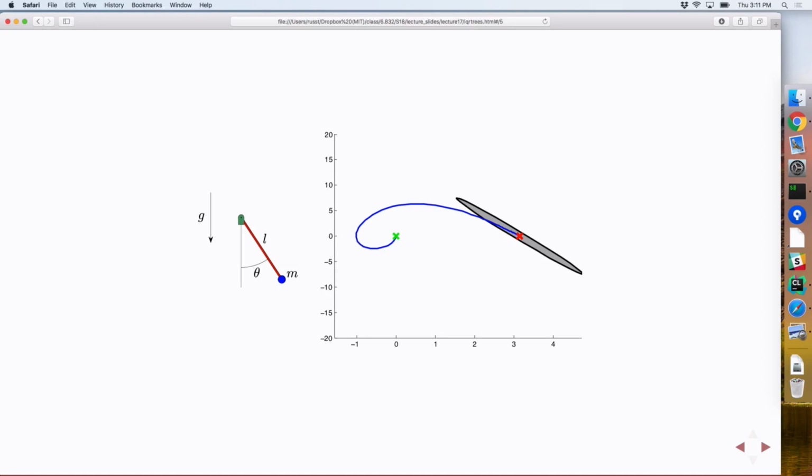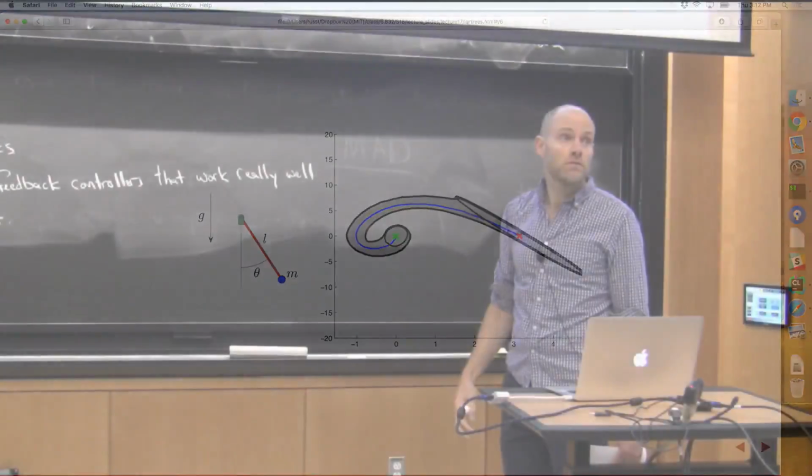And now I'd like to think about adding a new funnel, right? So what if I wanted a controller that goes from 0 and lands in the end in the final time, then I can do trajectory optimization to swing up from the bottom to the top. I can stabilize that with a time varying feedback controller, right?